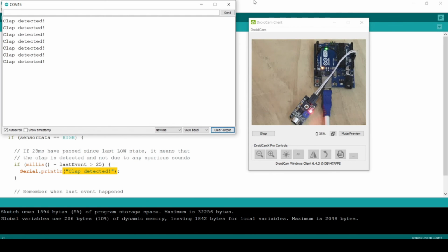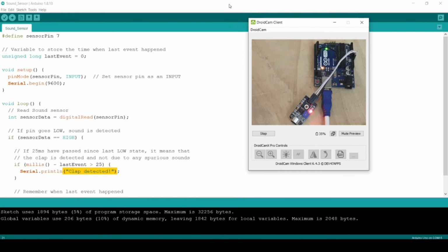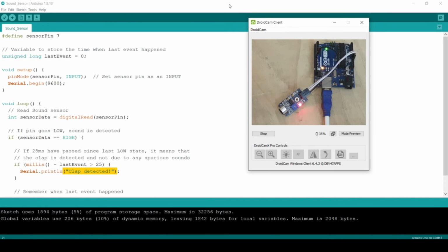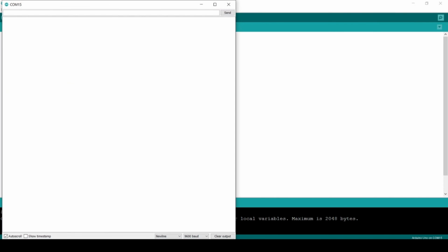The only thing here you can know is you have to calibrate the sound sensor for your clap signal, right? If you calibrate it for more value, then it is not going to detect the clap as I had done previously. So I am again rotating it in anti-clockwise direction. I will calibrate it for more signal. Again I will open my serial monitor.